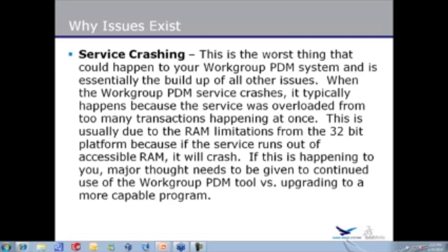Is there a maximum number of folders, subfolders, or files in a working folder for PDMWorks? That is a fantastic question. I'm going to talk about working folders a little bit, but let me tell you this. Windows gets really itchy if you have more than 2,000 to 3,000 files in a folder. That is just a physical Windows limitation. So if you've got a working folder where you're storing your files in, I would suggest trying to keep the number of files in that folder under 2,000 for the best type of performance.